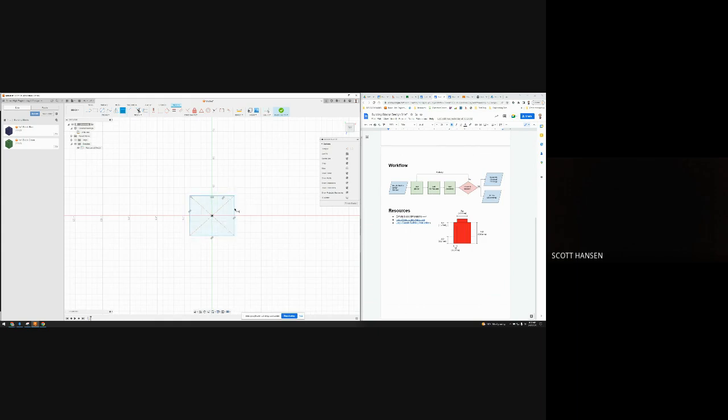Let's go ahead and set the size of the side. For this particular design, if we add up these little P units, each P unit is 1.6 millimeters. The width of this block is going to be 1, 2, 3, 4, and then one more on the side, 5 P units. And so in my dimensions, I can actually type 5 times 1.6. And that'll resize that side of my rectangle to be the correct size.